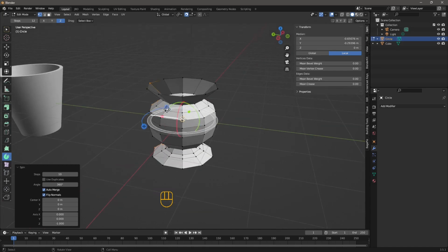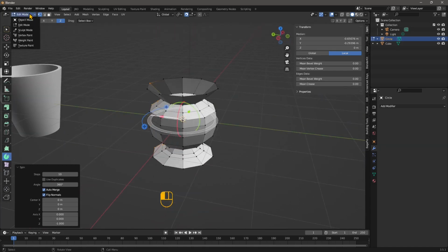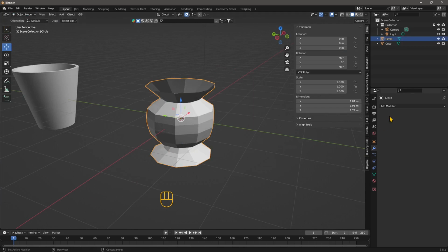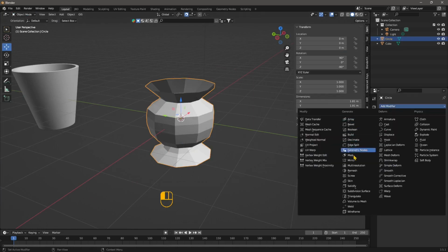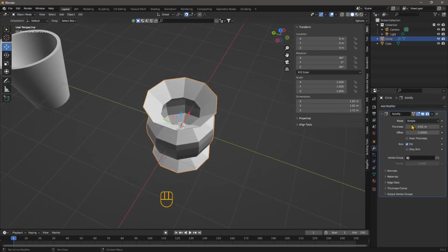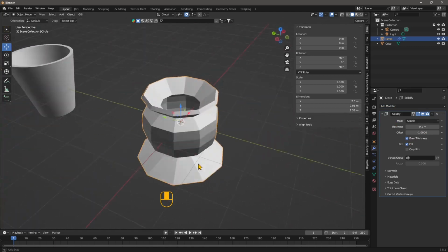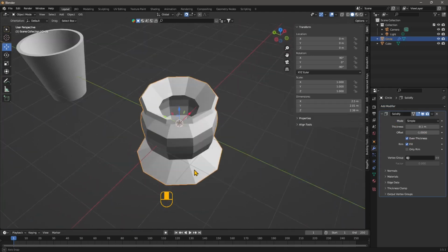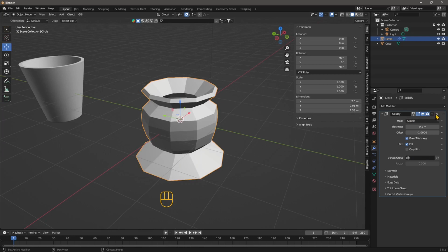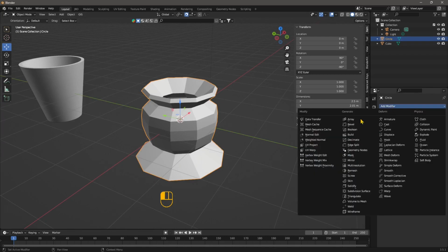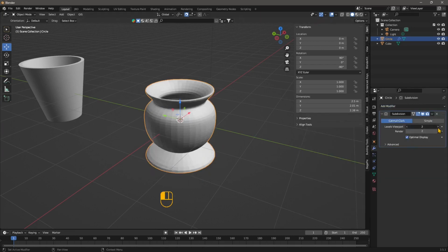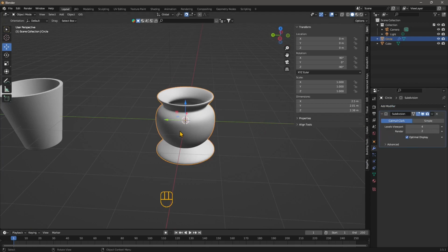customized shape. Now it's not a solid though, so to make it a solid, we can use the modifier here, Solidify. So it creates like a thickness to this. It can go outside or inside. It can be even with even thickness, and you can see it's looking fine. Now, if we want, we can use this as a low poly model. But if we apply the Solidify and then we use also the subdivision surface, this is going to become smoother and smoother, and it's going to look more like clay.